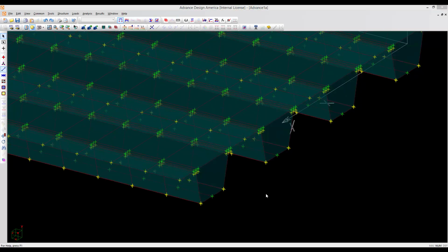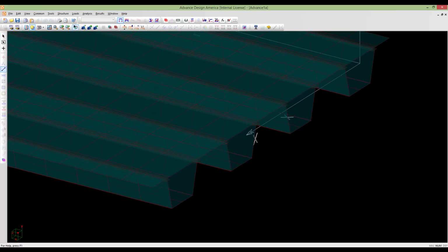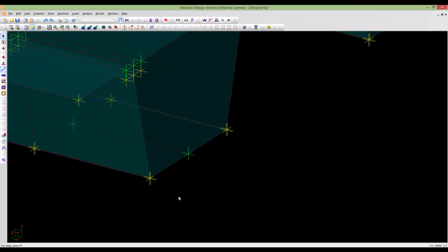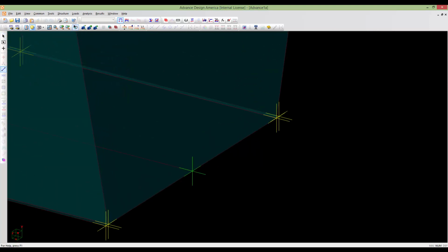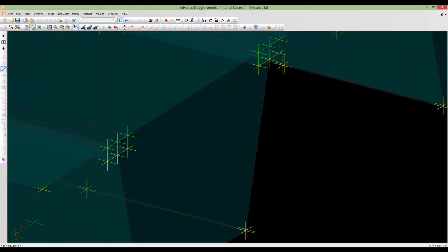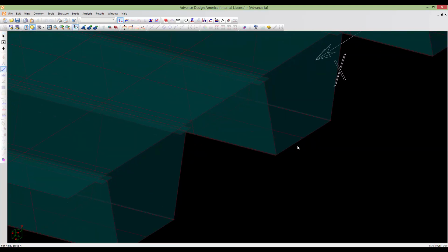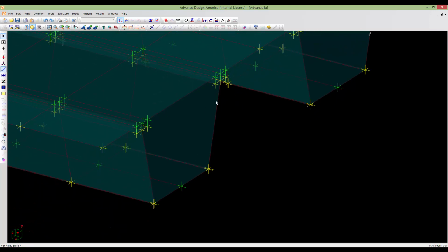In the next step, I'm going to add the transverse members and diaphragm frame, because right now we have the nodes for the box girder and we just need to define the nodes and the members between these nodes. So I will go to the addition mode and additional members and just click between the nodes here.